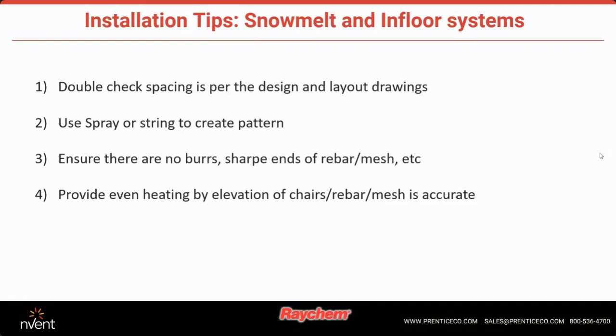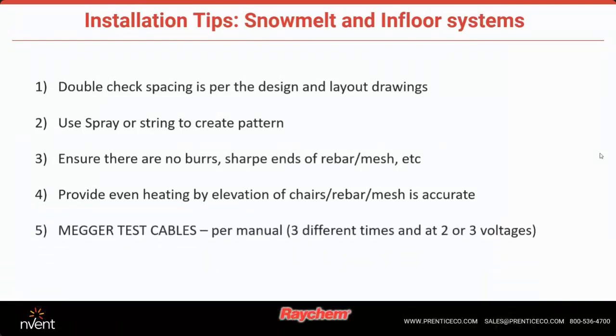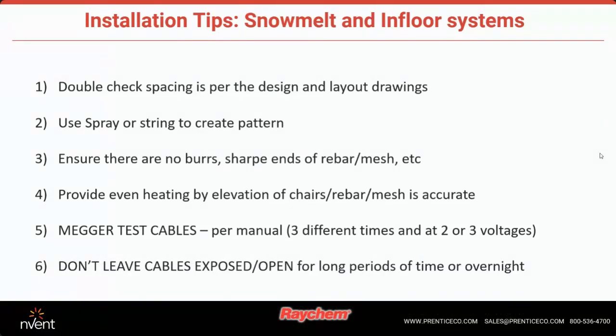So we do want to just make sure that you have an even level on those areas. Again, same thing applies. Megger testing, installation testing is very, very critical. Make sure you look at the manual, make sure you do that on all 3 different occasions and at the voltages that apply to the product.